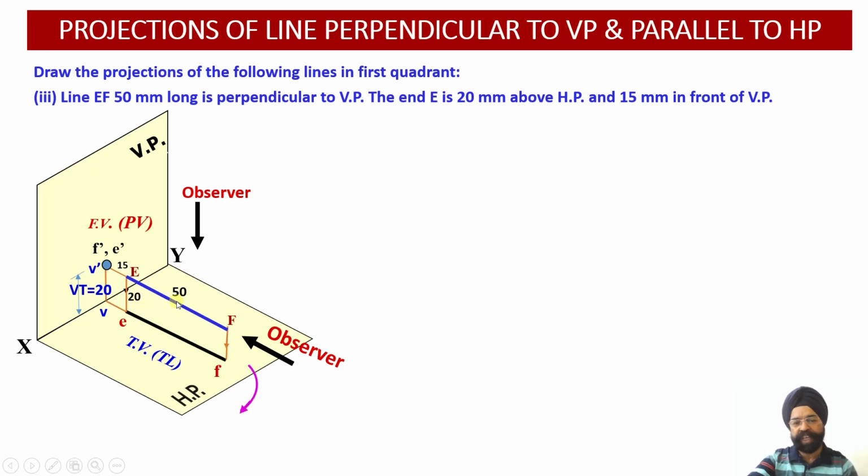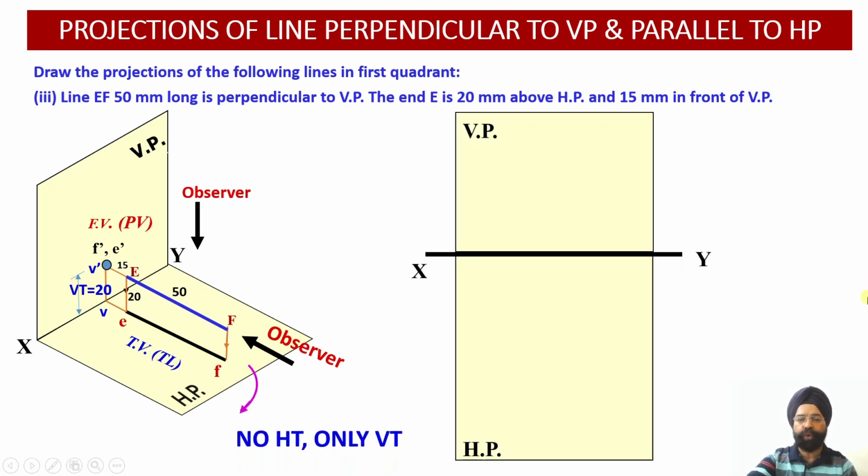Now since this projection and this projection, that is front view projections and top view projections that we have obtained, this one is front view and this one is top view. These projections are obtained in mutually perpendicular planes. We need to carry out the rotation of this horizontal plane clockwise downwards to be able to draw both of these projections on the same plane, 2D plane.